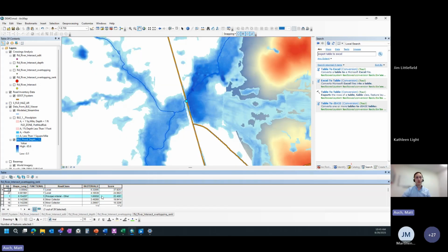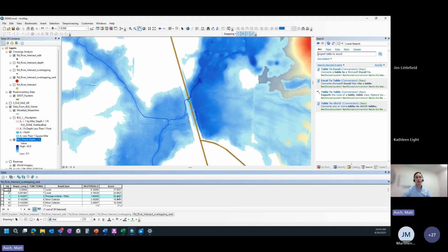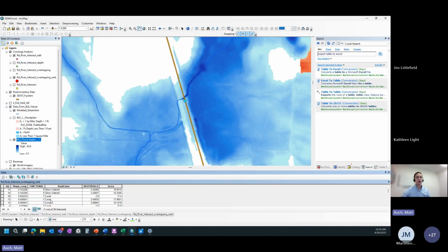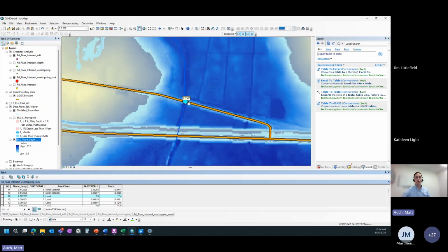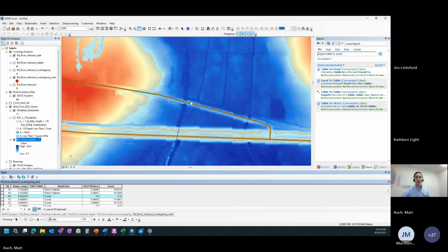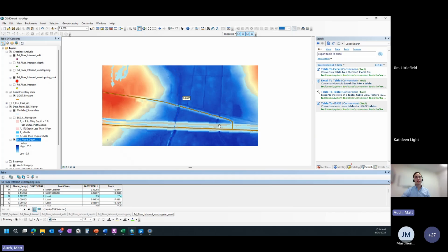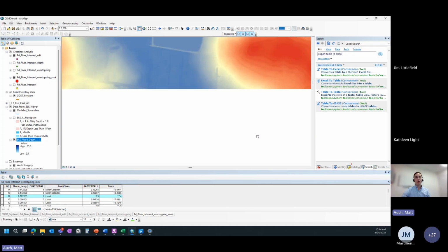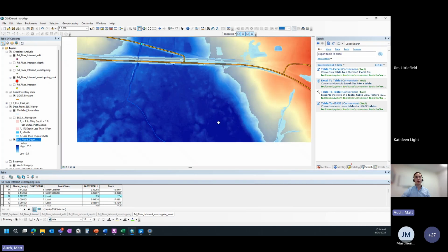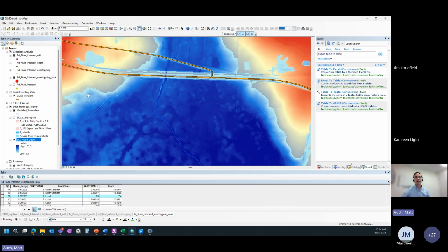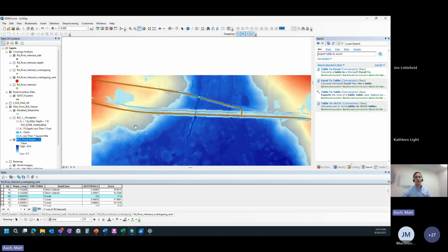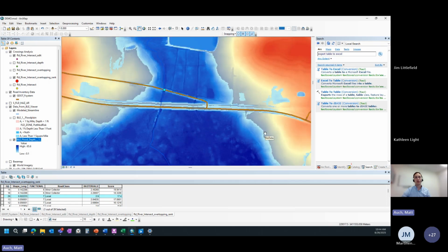Here this one was overtopping by 1.5 feet, but it's a more major road, and so it was ranked higher. And you can go through and look at what roads are getting flagged and maybe modify your criteria if something's not really making sense. But yeah, this is a really valuable way to take all of the assets and start to focus down on where's going to have the highest benefit to doing a project.